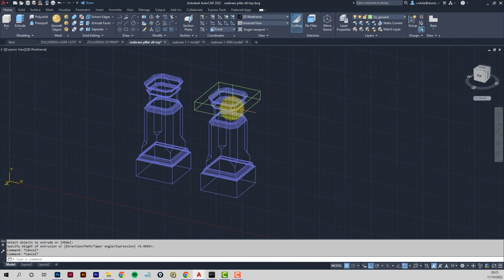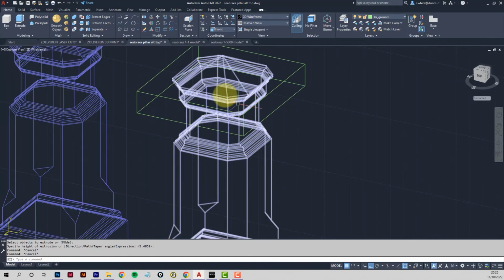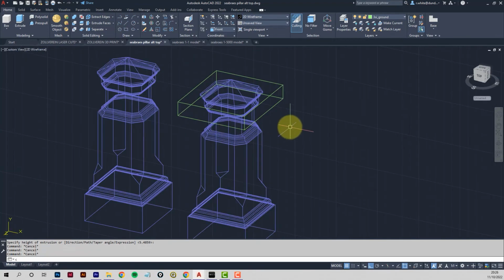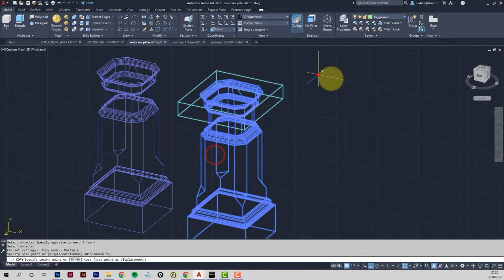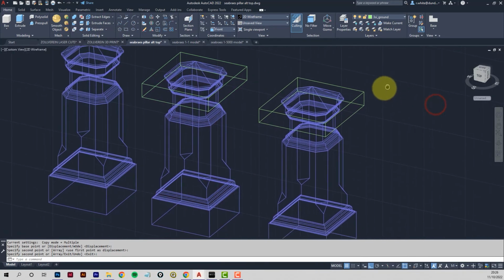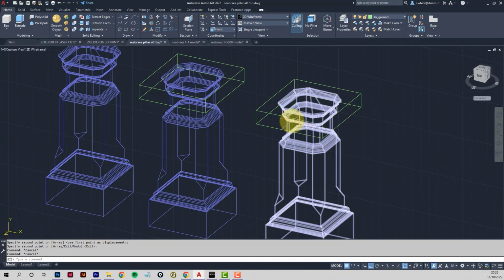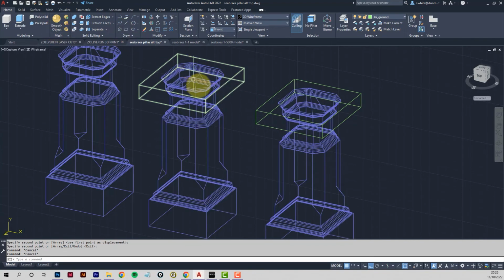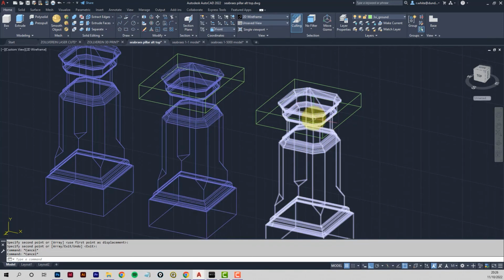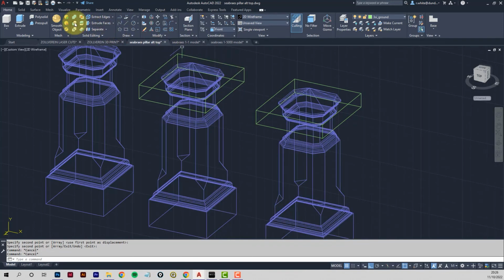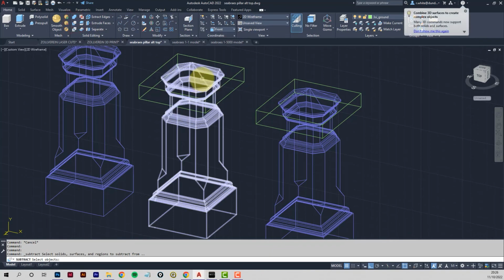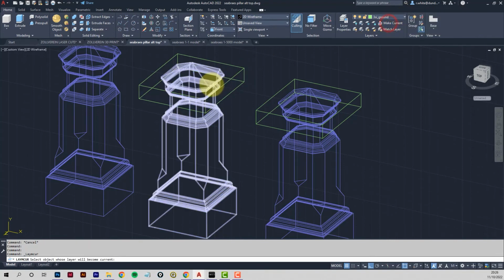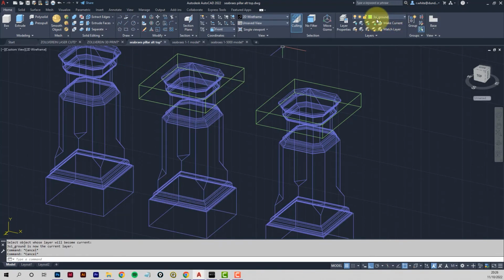Okay, now if we just extract this bit in the middle, we'll lose the other two. We'll lose those, but we need 3 pieces in the end. So what I'll do is copy this just now. Copy it again. Okay, so we'll do an intersection on both of these. So no, it'd be a subtraction on this one, but an intersection on this one. Okay, so subtract. Oh, let's just make this the current layer, so we keep the layer colour. Try that again. Make current.